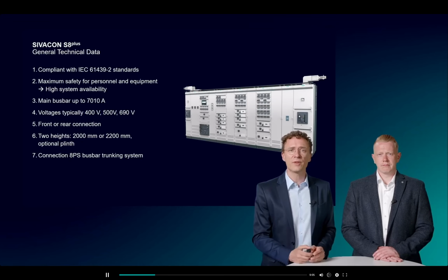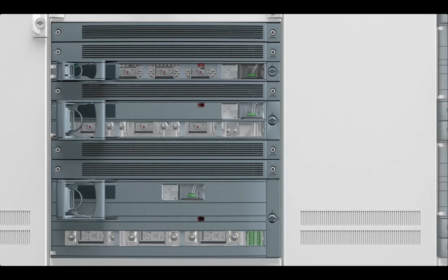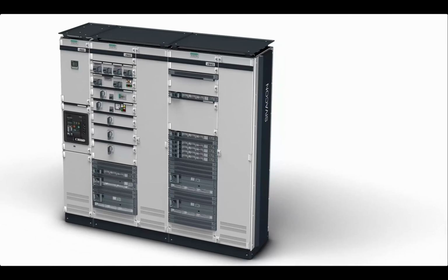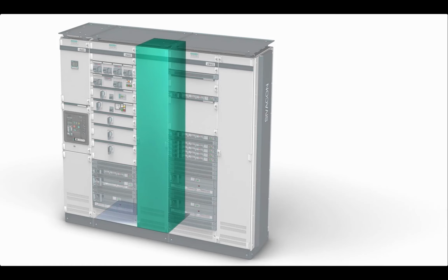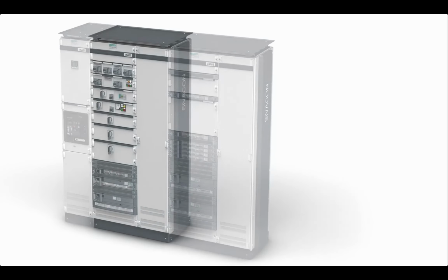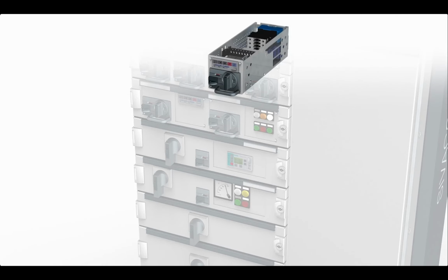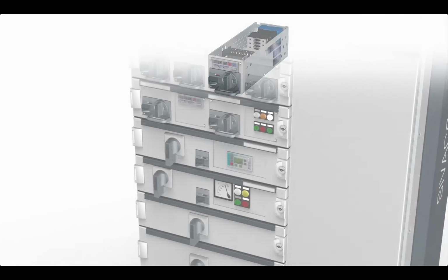You will see how this works in the following video. You see a combined instrument transformer, a combination of a current transformer and a voltage transformer in one device, because normally we need both measurements, current and voltage. Frequently changing requirements, this design offers the necessary flexibility, as well as easy and safe handling. The cable connection compartment can be positioned laterally or at the rear. And what you also see here is again the 3 phases. That means if we talk about one voltage transformer, withdrawable unit widths normally talk about 150 millimeters, so 3 devices, 300 millimeters, one per phase.